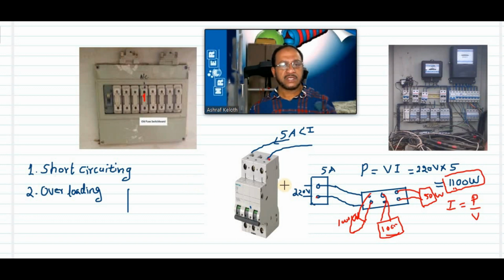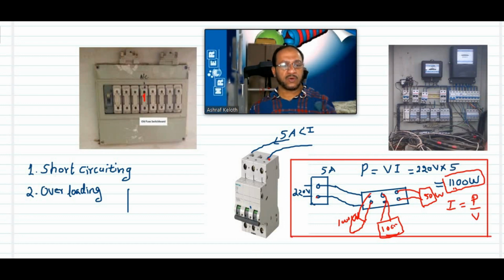And one more point. Suppose right now this is your bedroom, and this is the wiring of your bedroom. Suppose in your room some polishing work is going on. They are polishing the marble, and the polishing machine is of power 2000 watts. Can you plug that 2000 watts machine in the plug here? No, sir. No, because maximum allowed power here is how much? 1100 watts only.